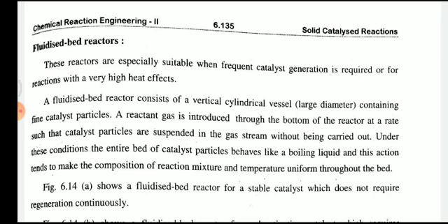Then a fluidized bed reactor consists of a vertical cylindrical vessel, of large diameter, containing fine catalyst particles. The reactor gas is introduced at the bottom of the reactor at a rate such that the catalyst particles are suspended in the gas stream without being carried out. Under this condition, the entire bed of catalyst particles behaves like a boiling liquid, and this action tends to make the composition of the reactor mixture and the temperature uniform through the bed.